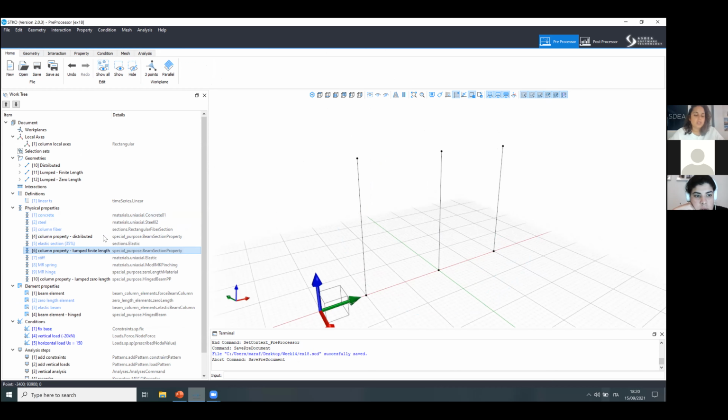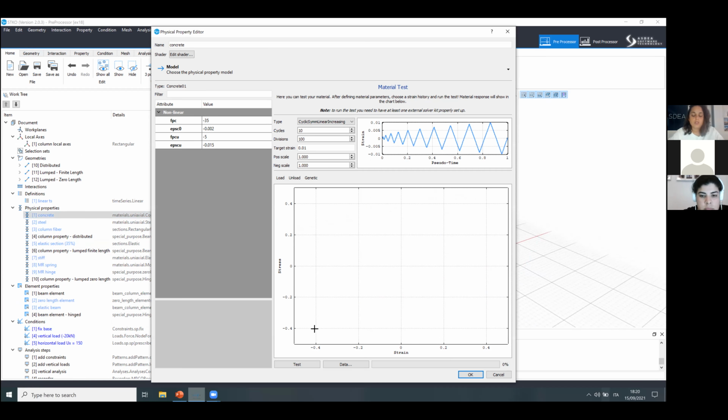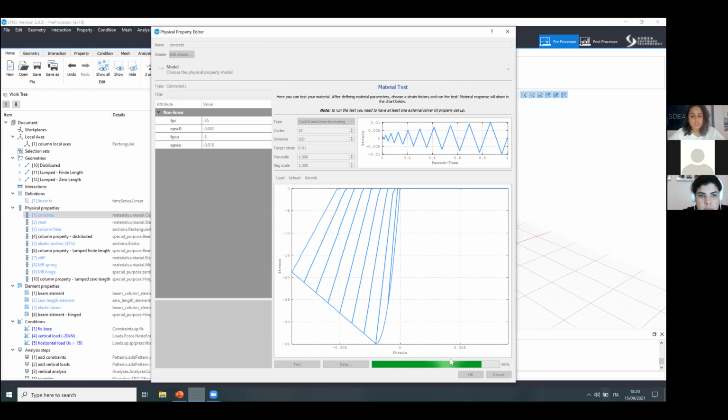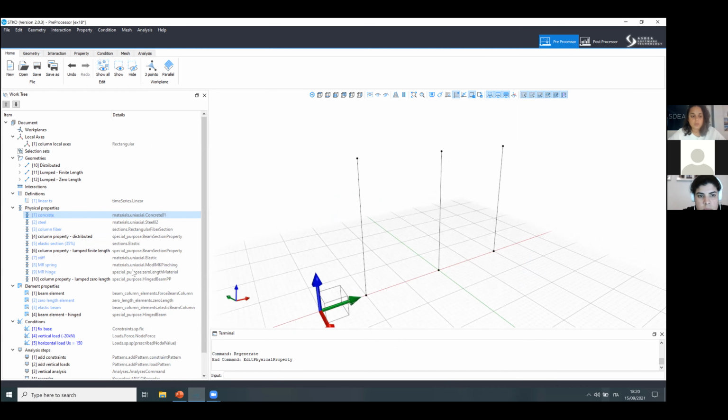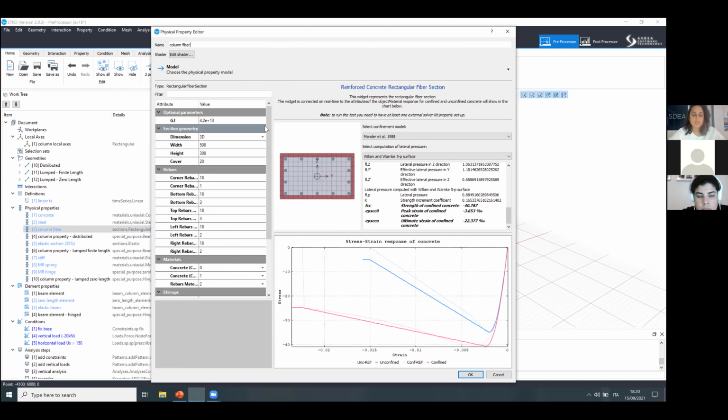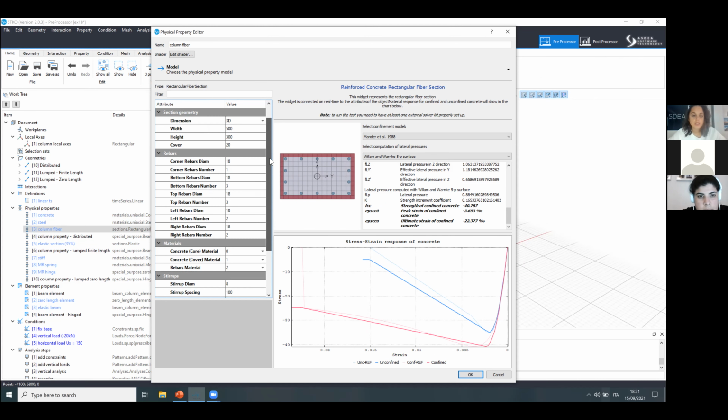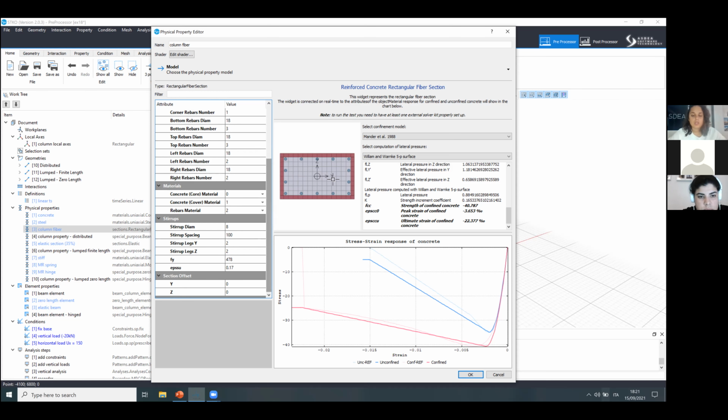I just wanted to point out that we talked last week about how to calibrate these kinds of parameters, so how to build your concrete and your steel and also hysteretic or pinching materials. We discussed, I don't know if we discussed the rectangular fiber section, maybe we can do it a bit now. There is this editor that we developed in STKO, in which you can define customized rectangular fiber sections by applying dimensions, reinforcement configurations, materials, and also transversal reinforcements and offset.